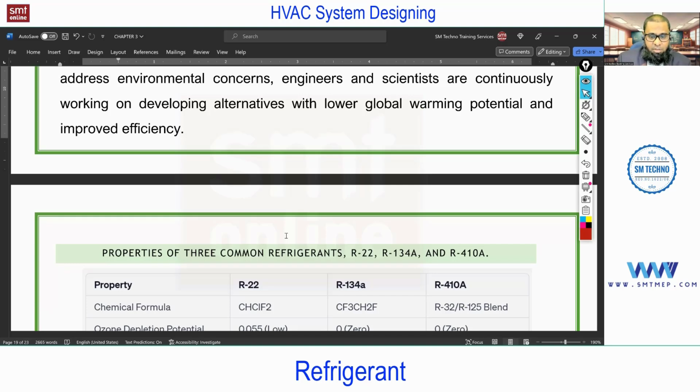Take the VRF system. VRF pipe sizing is a responsibility of an HVAC design engineer, and the refrigerant, no, that will be taken care of by the vendor. Apart from this, even for VRF, in actual practice many special vendors or manufacturers take care of even the pipe sizing. But again, as an HVAC engineer, you should know the pipe sizing of VRF. The pipe sizing of window, split, and ductable systems is not a responsibility of an HVAC design engineer. That is a responsibility of the manufacturer.